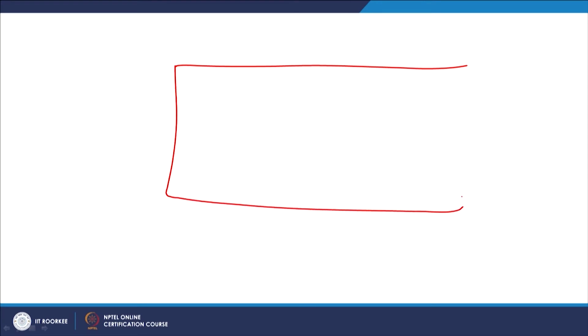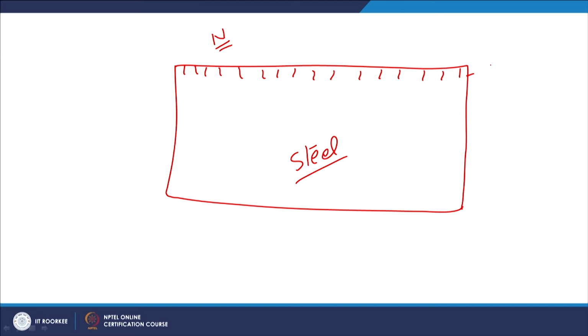For the nitriding purpose, in the steel component which is subjected to the nitriding process, the nitrogen content of the surface and near surface layers is enhanced. It can vary up to 5 to 6%. When nitriding is carried out, the objective is to form nitrides which are hard and stable, and at the same time do not enhance the brittleness and increase the cracking tendency.